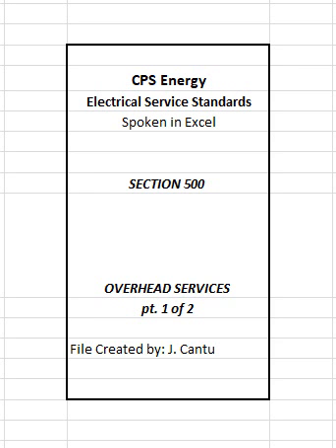506.2 Approved types. Service raceways enclosing service entrance conductors shall be galvanized rigid metal conduit, RMC, intermediate metal conduit, IMC, or electrical metallic tubing, EMT, type raceways. Exception 1. EMT is not permitted where used as a service mast. Exception 2. Bus risers are permitted where service entrance conductors exceed 3 conductors per phase, refer to Article 509(5).